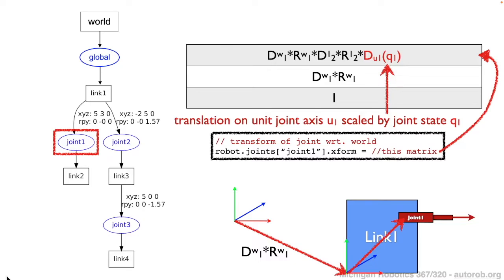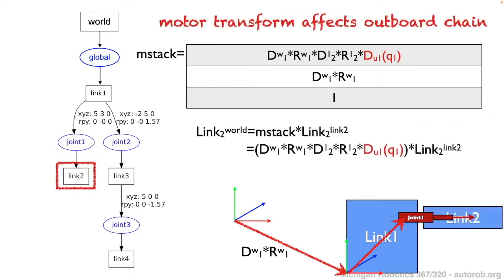And once again, by composing that composite transformation matrix, we will then know how the remaining portions of this particular branch in the kinematic tree can be positioned within the world coordinate frame.